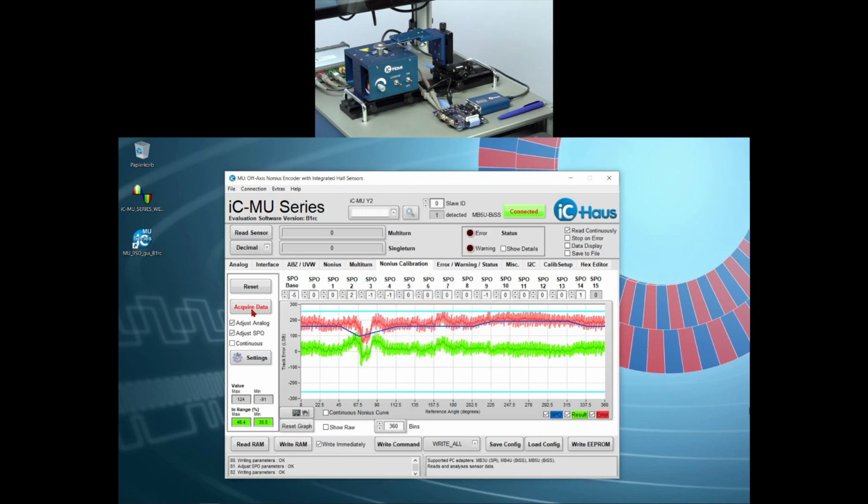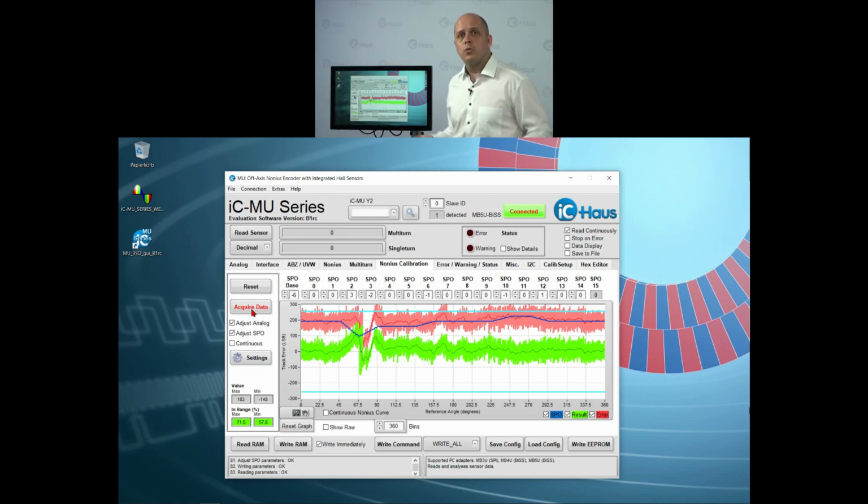It gets much wider, much thicker. If you see something like this, you know there's noise in the system, and usually this is due to your chip to code disk distance being a little bit too high. Because the magnetic field strength will be lower, the amplification has to be increased in the chip, which then causes more noise in the system.